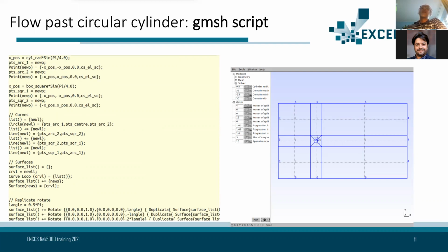Gmsh has some ability. The drawback is that you have to go from any triangular mesh to the hex meshes, which can be kind of okay in 2D with Gmsh. In 3D, it's more problematic. It is not a simple part of the whole workflow. So there is no just black box. You put it in and you get output. It doesn't work this way.